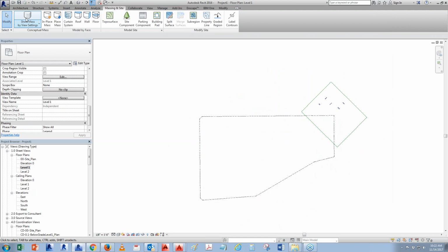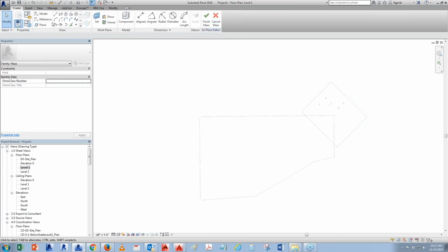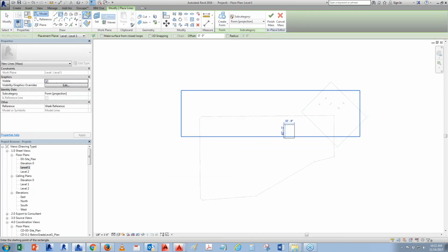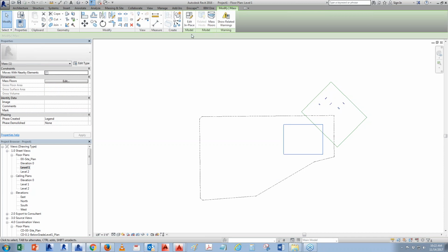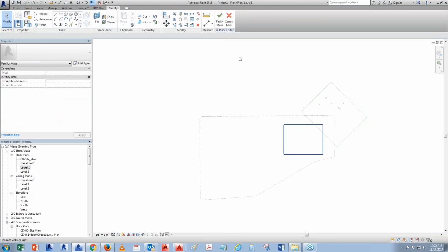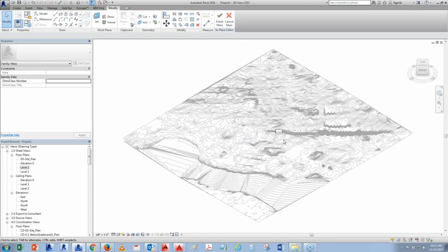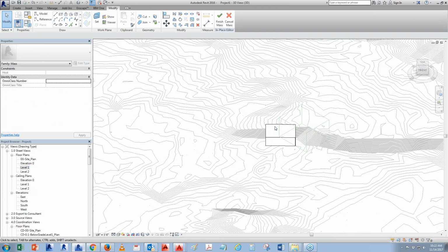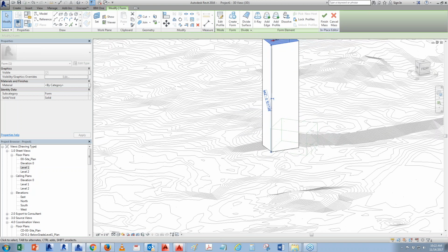Okay, so now the next thing you want to do is create massing. So we click on this and say show massing and create a massing in place. Here I'm just going to go tower 1. Okay, I'm just going to do a simple box. Just say sure. Finished. Okay, that's fine. And then here, edit in place. You want to create a form. Okay. And now what you're going to do here is that you're going to select it and you're going to move it up, let's say